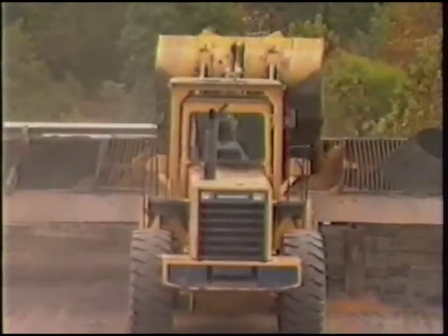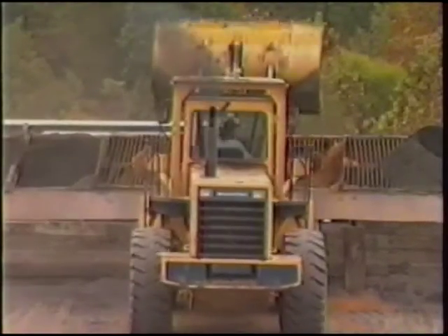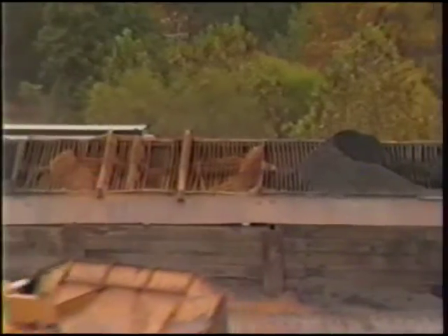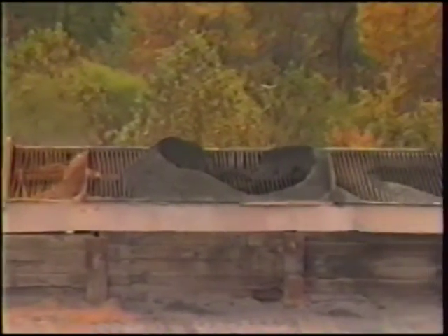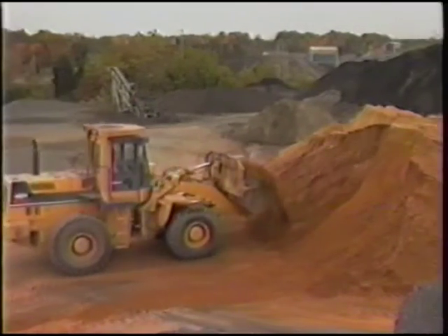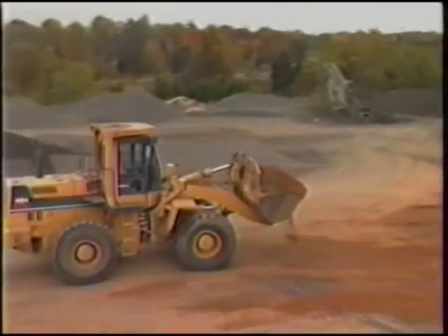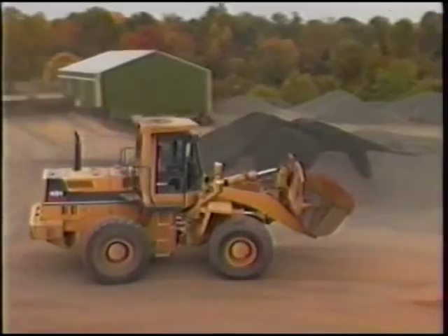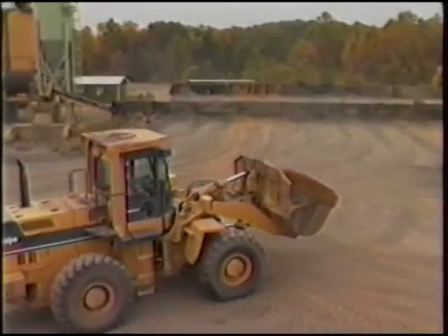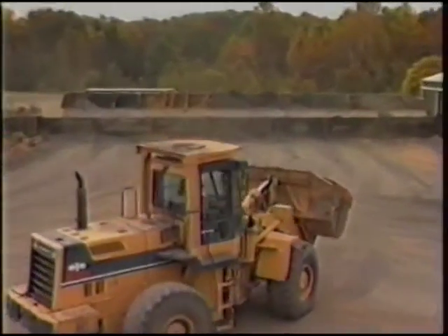Aggregate stockpiled at the plant is loaded into bins where it is conveyed into the plant for asphalt production. In order for the asphalt concrete to meet specifications, the aggregate going into the plant must be clean and well blended. Whether at an end-user's production site or at a staging area, it is critical that proper stockpiling and handling techniques are adhered to maintain the quality of the product.